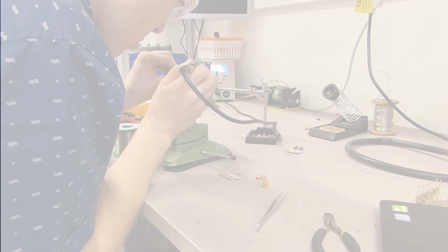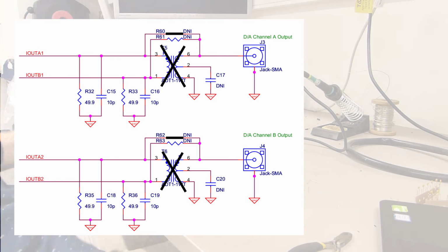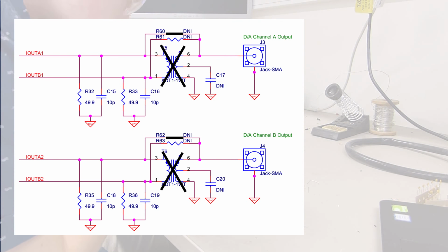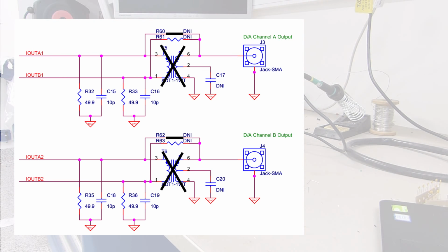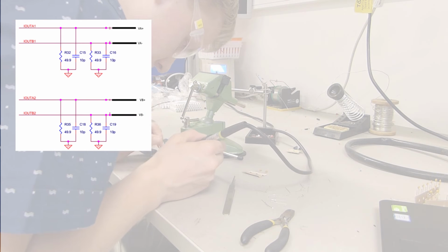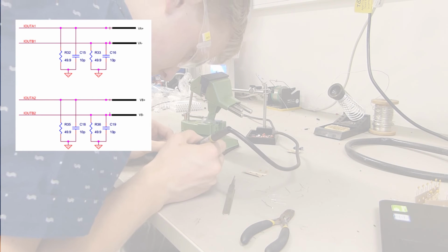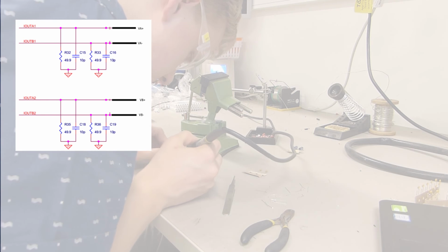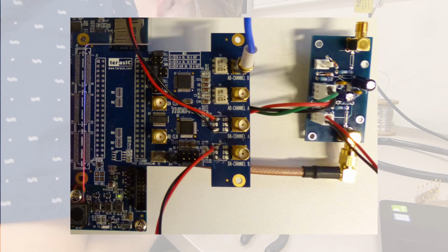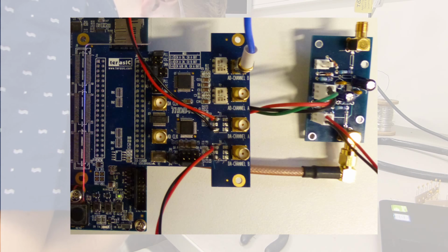Another significant contribution that was made was generating this dual channel differential amplifier. It was necessary because we had DC offsets on our single-ended outputs from the ADDA daughter card. For integration into the lab, the signal needed to be amplified a little bit, but also needed to be centered around 0. This differential amplifier was designed to be plugged in to where the ports were for the old transformers that we removed from the original ADDA daughter card.